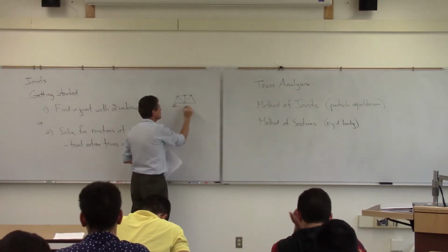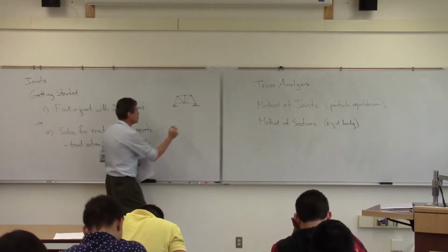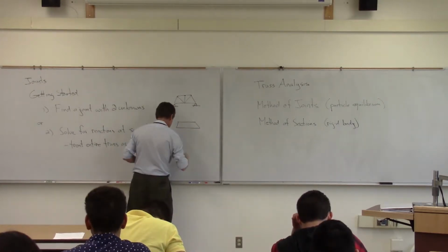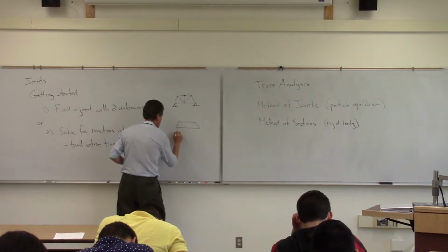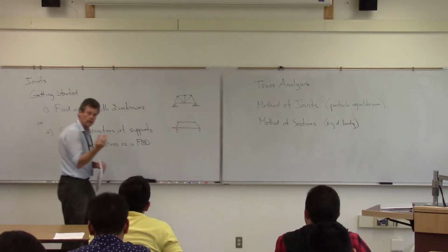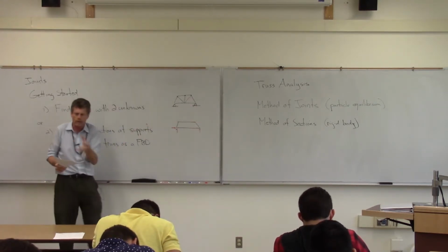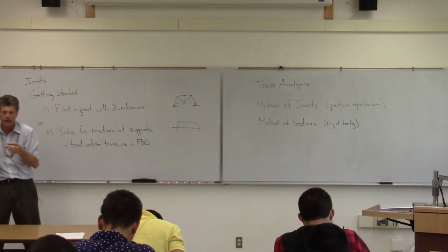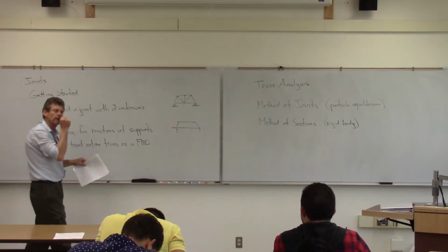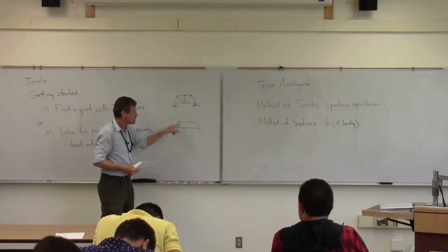But the thing has to be on the ground. So what we're suggesting here is that we treat this like a free body diagram. Notice there are no internal members here. Remember, the definition of a free body diagram is the external boundary. I don't care what's going on the inside. The only thing I care about on the inside is maybe weight, but those truss members I don't care about.